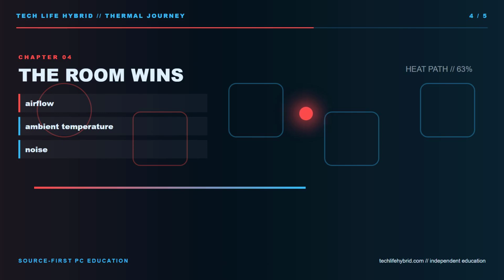Before tuning, confirm socket compatibility, cooler rating, physical fit, fan direction, pump connection, and clean vents. Establish a repeatable baseline. Change one variable, such as a fan curve or mounting correction, then run the same test again. Do not compare unrelated workloads or force every fan to maximum all day.